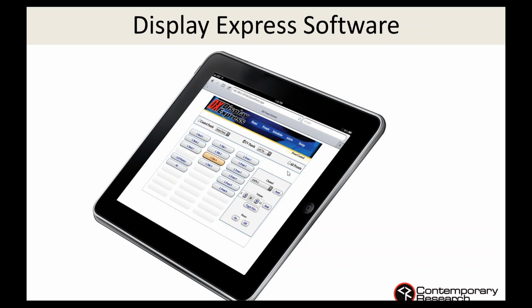Basically, in this software called Display Express, you set up your channel list, you set up the names and addresses of the control boxes in the system, and then you make presets which say, okay, this group of TVs or this TV will do this action when I push the button, or I schedule it. And so in the morning, all the TVs turn on, hallway TVs go to this channel, lobby TVs go to the signage channel, some of the other TVs go to the weather station, and you can have a daily schedule, manage the video throughout the system.